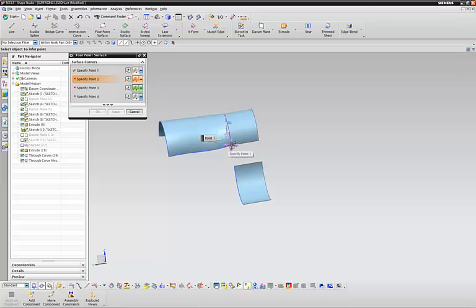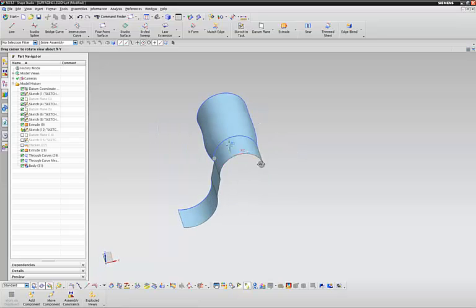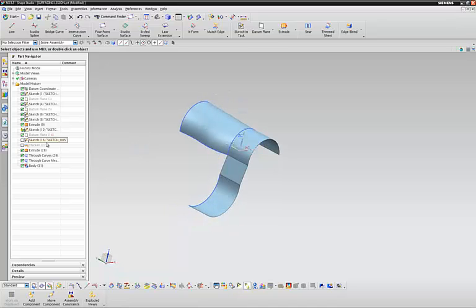Our second point, third point, fourth point. You gotta do it in the shape of a square or rectangle, otherwise it will generate a weird hexagon shape. That's a data plane, another sketch, added thickness.